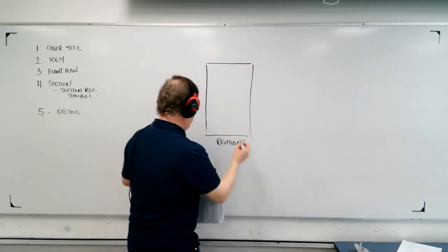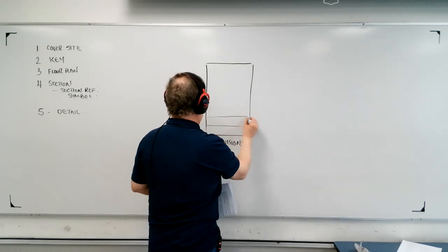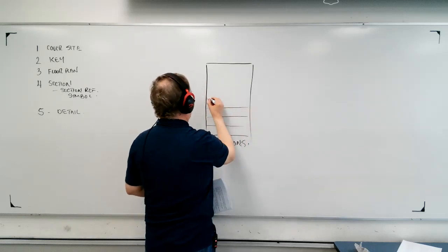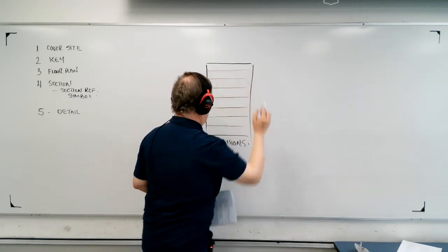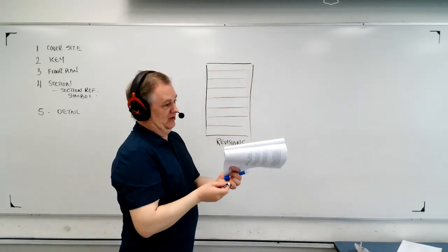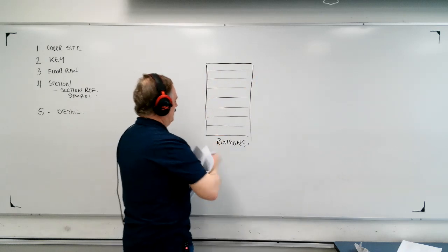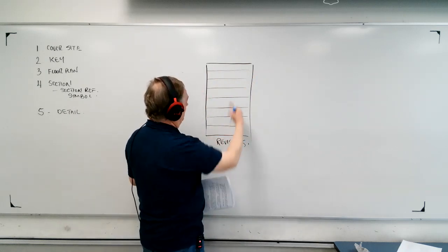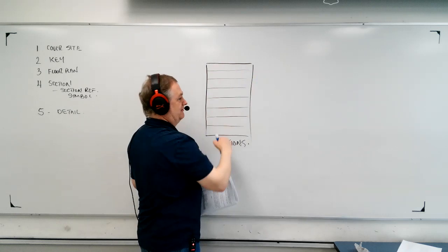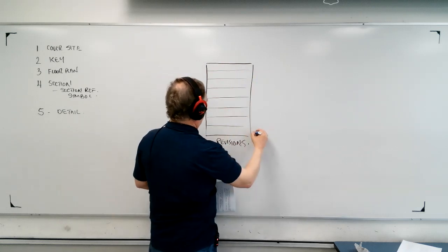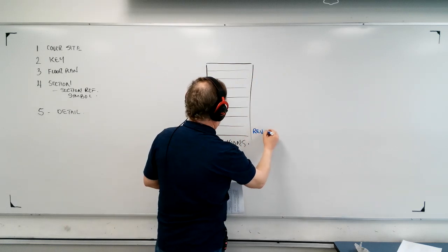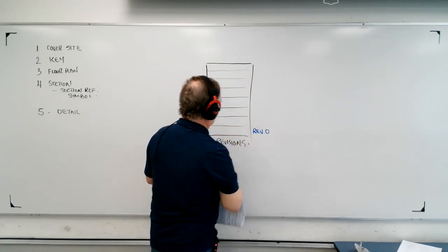I can't say that every set of drawings that I've ever seen is the same, but I can definitely say that almost all of them have been the same. And they start at the bottom. They'll put in a blank table of rows, and they start at the bottom, and they'll call this revision, sometimes 1, but sometimes even 0.